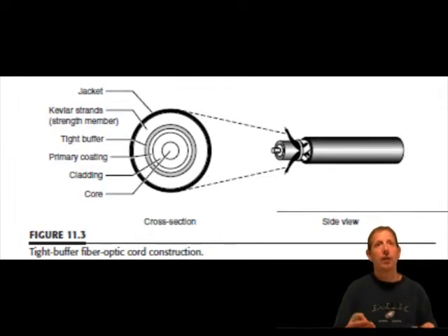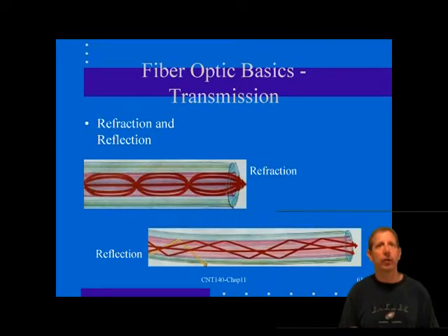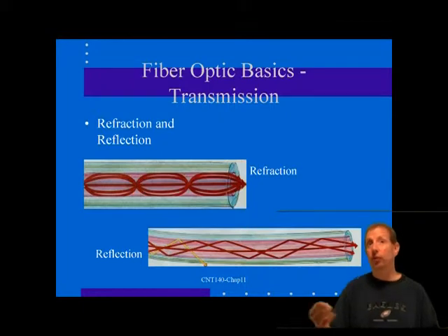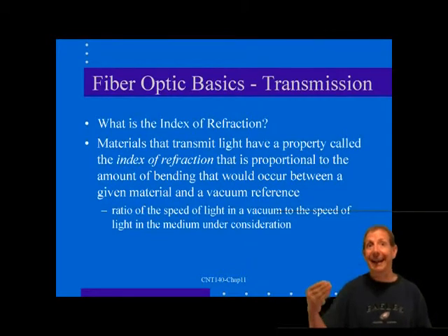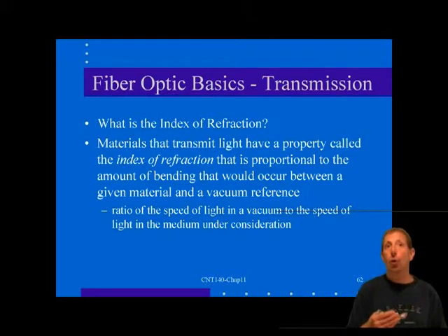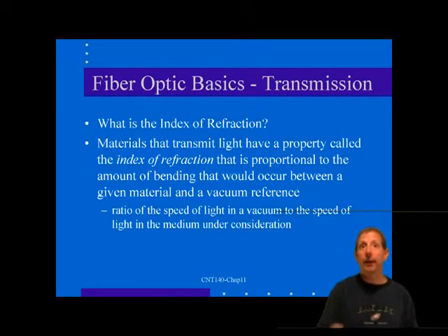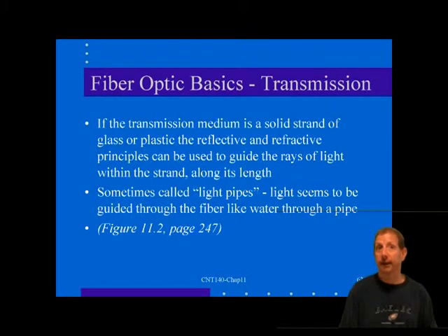A multi-fiber tight buffer cable has two or more of the buffered fibers, which may be additionally covered by an individual jacket and one or more spacer or strength members. During installation or termination, the outer jacket and the fine strands of the strength layer are removed with a sharp blade or a cable stripping tool, leaving what appears to be a small diameter flexible strand. Now, this strand is the bare fiber consisting of the fiber core, cladding, and primary coating, plus the tight buffer.